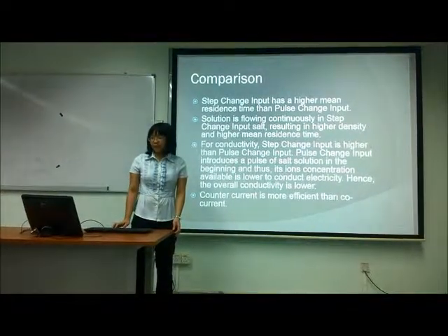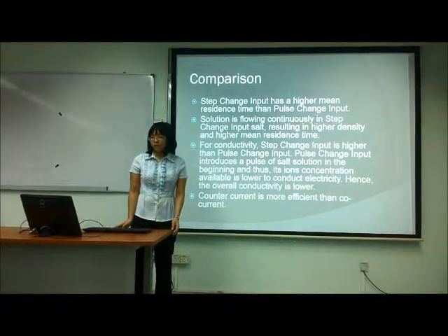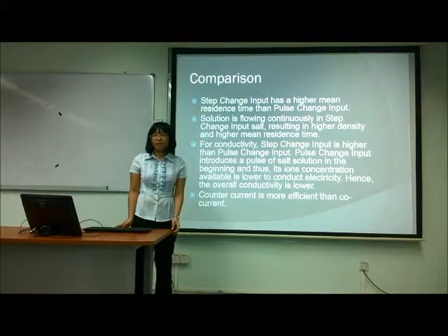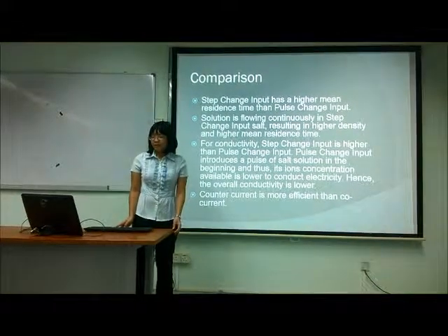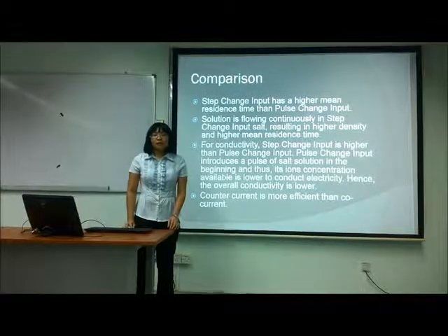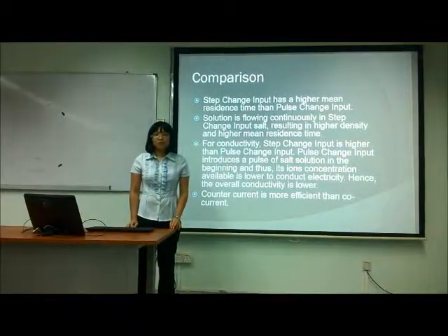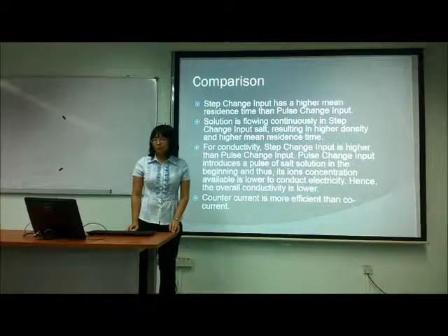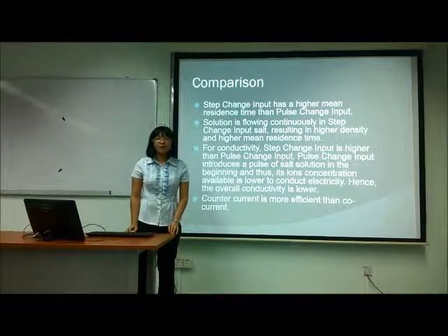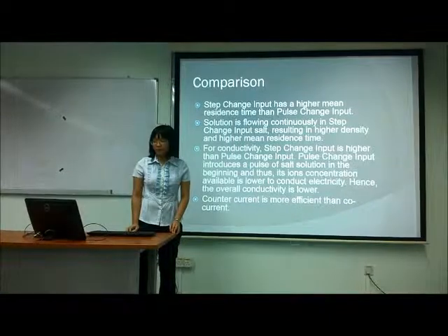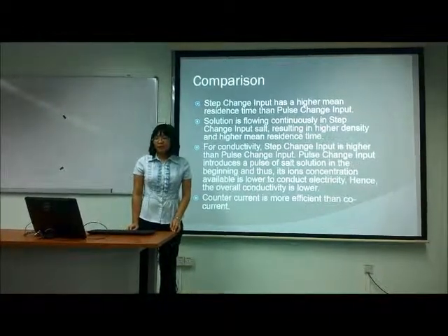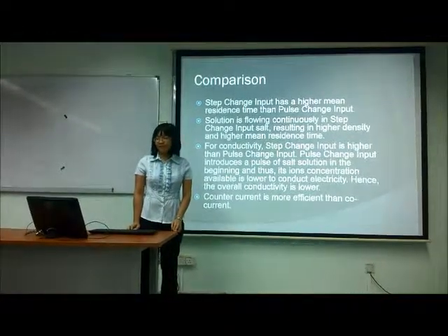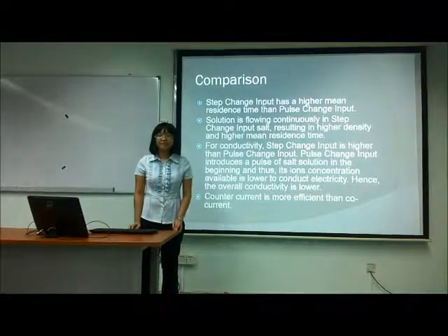And in conductivity, we can also see that step change input has a higher conductivity than that of pulse change input. This is explained by the fact that when the pulse of salt solution is introduced into the reactor, the ion concentration available to conduct electricity is lower, thus the overall conductivity is low. In conclusion, this makes counter current more effective than co-current flow.